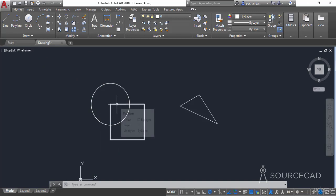Now here in this case, we have a simple polyline. Let's convert this one into also a region. So I'll select the region, I'll click on this and press enter. We again have a new region here. Now I'll convert this object into a region. In this case, you can see that we can select it separately. Let's now go to region tool and select all of these objects and press enter.